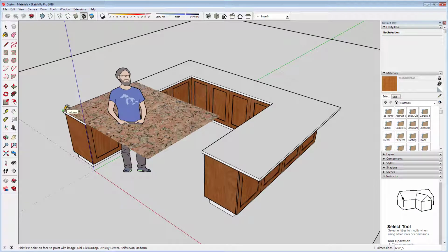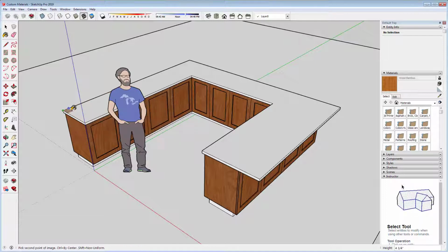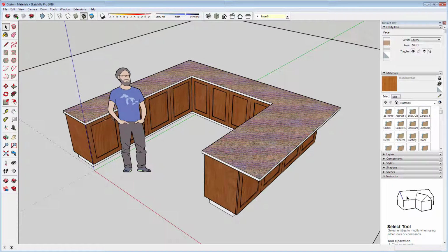So my recommendation is to start in a corner and then drag it out until it feels like it's about the scale that it might feel like in real life. We can adjust the scale factor later on, but something around that size doesn't look too bad. So I'm just going to click there, and you can see then it fills in the rest of the surface.